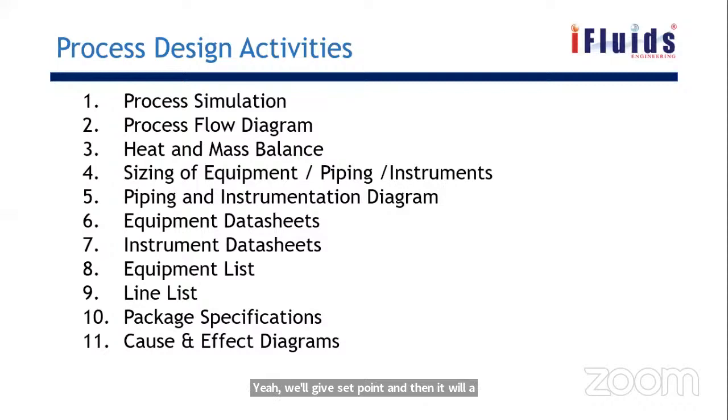If we have an inlet valve, we close the inlet valve. Or we can close the incoming source. If we have multiple users, we close the inlet valve. If we have only one user, we can directly stop the pump. Enough, stop, level is achieved.